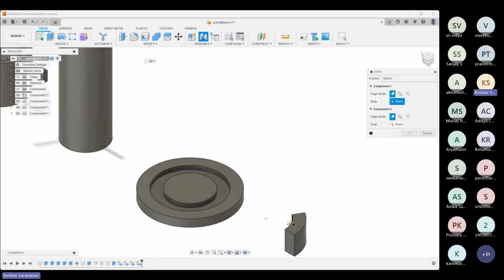it shows me an X to the left. That is the center of the arc, the center from which I drew the arc. If I actually move my mouse over there, it'll disappear. But you'll notice on the left, there is this cross that denotes the center. If I want to select that cross, what I have to do is hold Control so that the cross doesn't disappear. So right now I have Control pressed down on my keyboard. I wish I could show you that somehow, but unfortunately I can't. So now I'm able to select that cross.